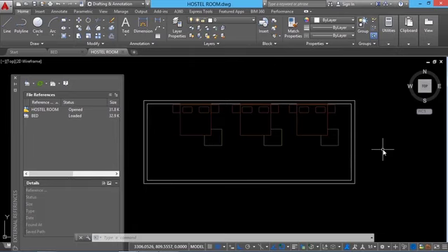It can be in any computer in a local area network, in a web server located anywhere in the world. Imagine the editing on this particular bed is done by a furniture designer who is sitting in some other computer. As and when he saves the changes periodically, that change will get updated into the current drawing. And that drawing will never become a part of this drawing. And this particular drawing is dependent on that drawing, because of which you have to take that particular Xref file along with this file if you want to relocate this file to a different location.